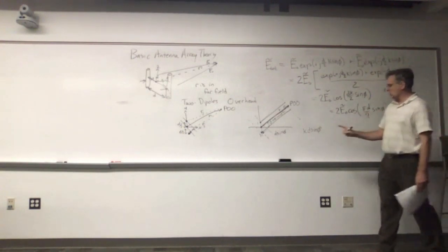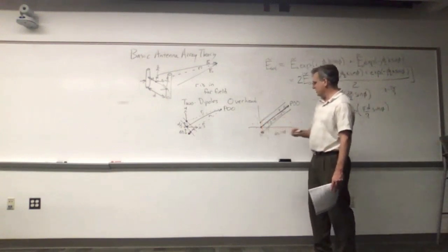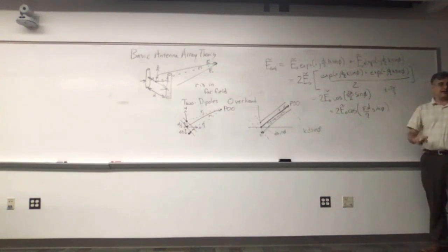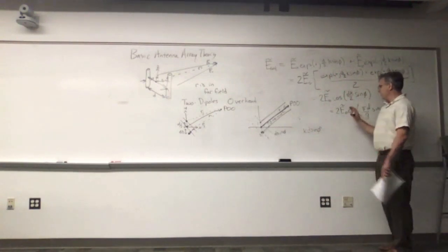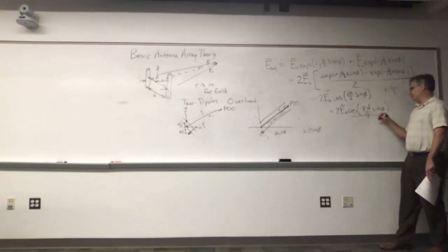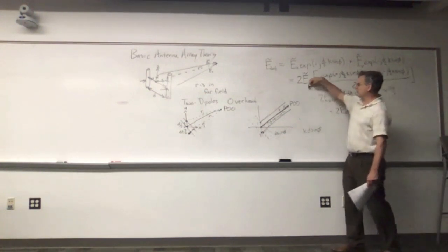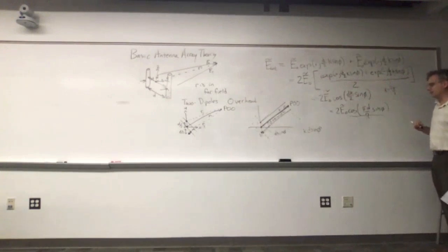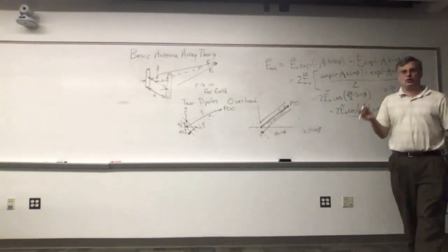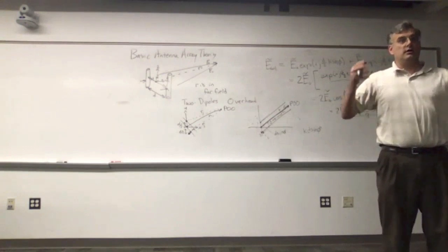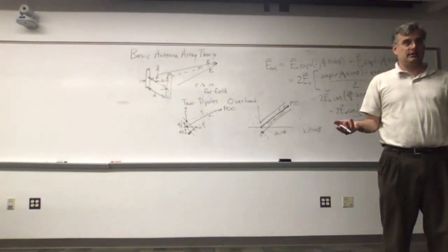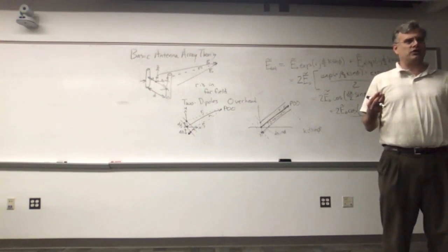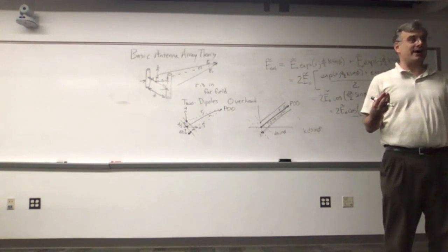So even though the individual elements are radiating the exact same amplitude, and in this case they're starting out with the same phase, we'll learn about arrays that don't necessarily do that, I'm getting significant amplitude changes as I sweep my observation in phi, changing how I look at this system. It's interesting because that means I can take any arbitrary number of omnidirectional antenna elements, and by placing them at different points in space, I can make some radically directional or at least some really messed up looking antenna patterns.